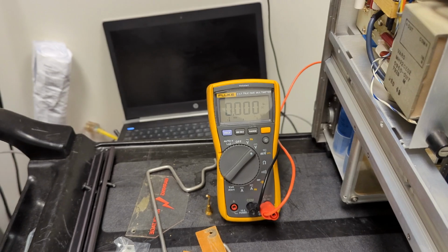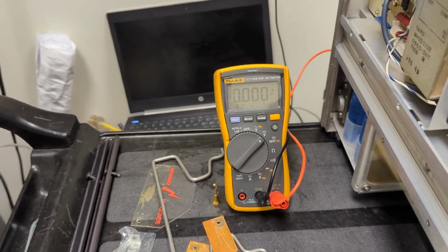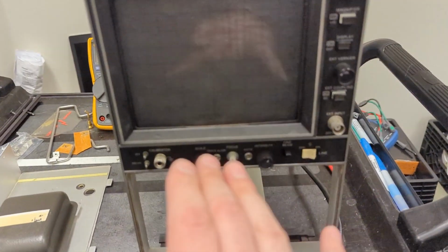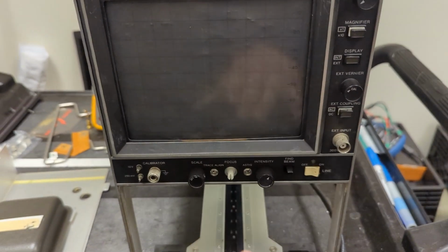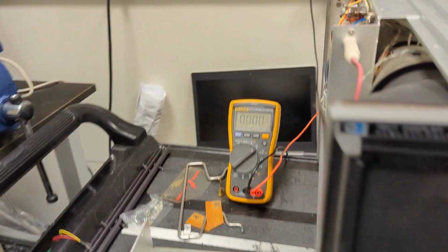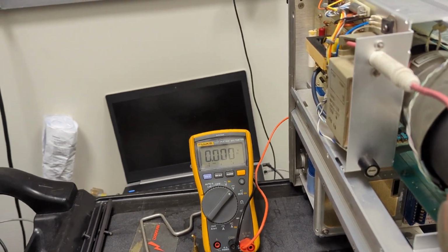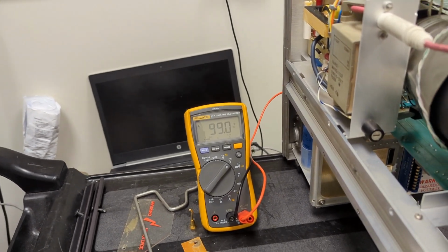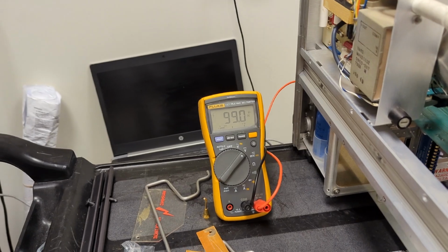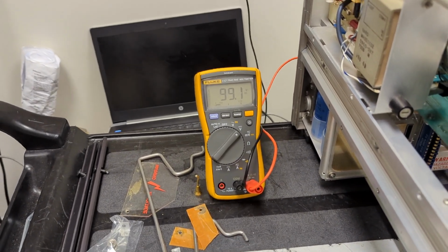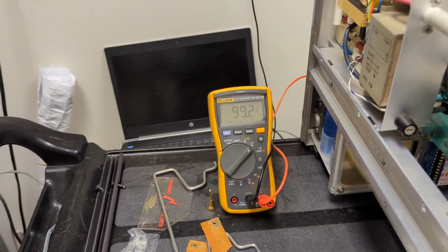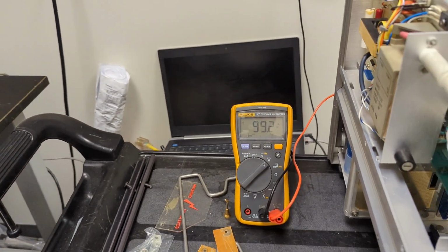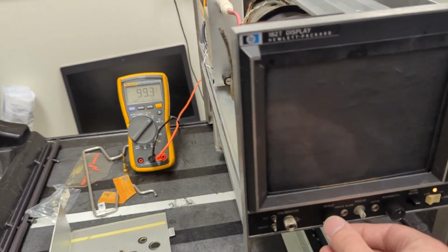So I've got the meter connected to the 100-volt rail, positive, and let's power this guy on. I have the scale, intensity, and focus controls all the way counterclockwise to start, but let's see what happens. Okay, and I should have realized that setting those rails bang on without all the load connected, they would be a little bit lower than they should be, but 99, I'll take that for now. But let's try.